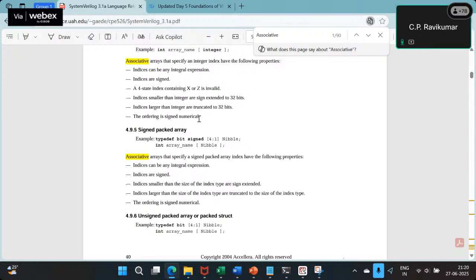Integer is there, real is there, and I think enumerated was also there in Verilog. Then all these things are new: short int, int, etc. Reg and wire were there. So reg, wire, integer, real, enumerated. To my knowledge, that's about all. Other than that, everything else is new.